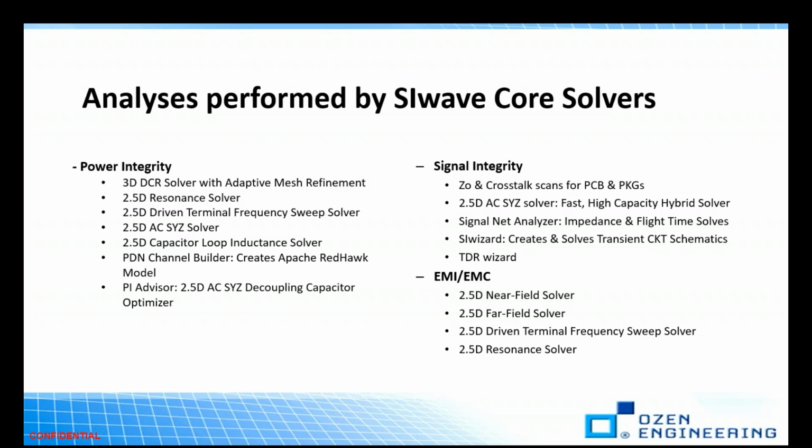Specifically for power integrity and signal integrity, SIwave has these core solvers to tackle the problem. For power integrity, we can utilize the 3D DCR solver with adaptive mesh refinement. And speaking of mesh refinement, it's another flagship technology within the ANSYS electronics suite.